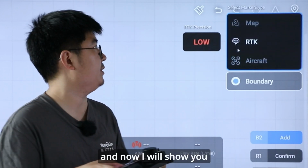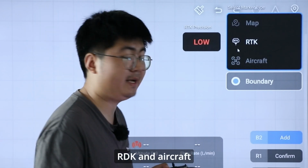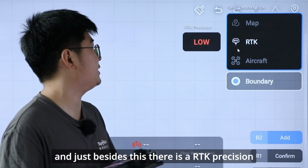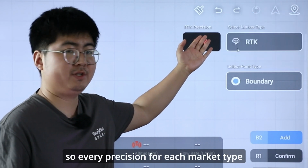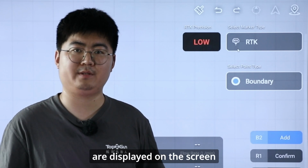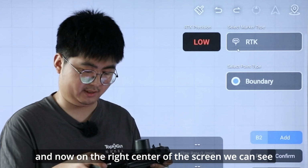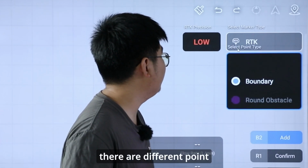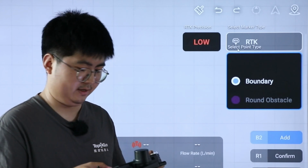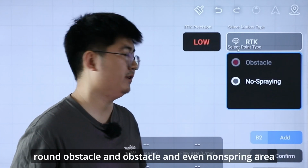Now I will show you. You can see there are three different types: map, RTK, and aircraft. Just beside this, there is an RTK precision, so the precision for each marker type is displayed on the screen. Now, on the right center of the screen, we can see there are different point types we need to use in operation. You see there are boundary, round obstacle, and even non-spraying area.